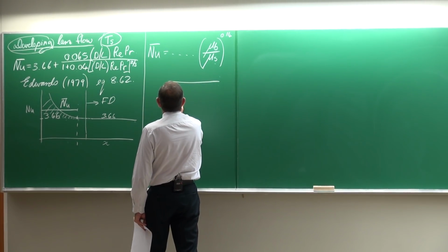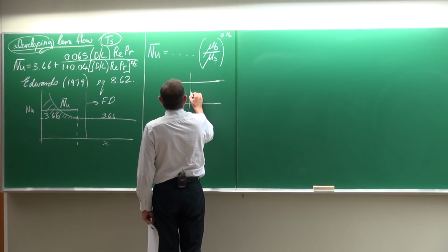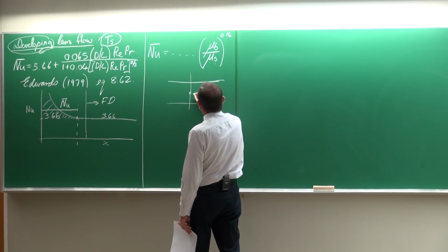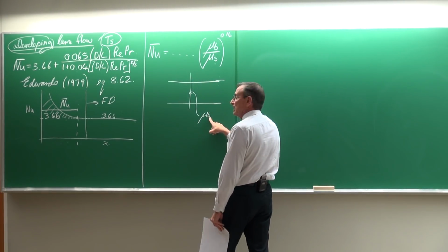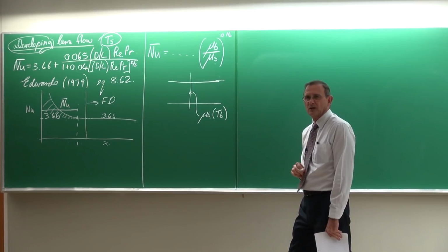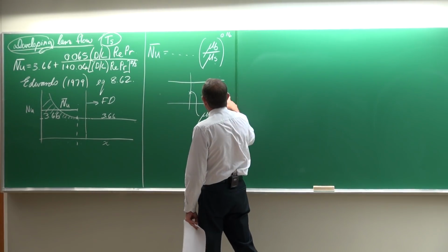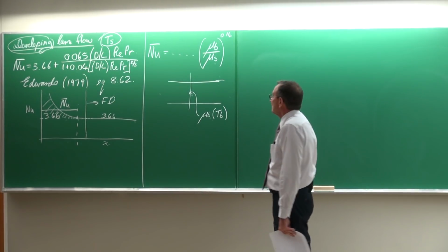It is about the fact that if that is your internal forced convection case, and that is the bulk temperature, so it means that the viscosity you're going to get will be based on the bulk temperature. Okay? So you're going to use the inlet and the outlet, get the bulk, and then you're going to get the viscosity there.